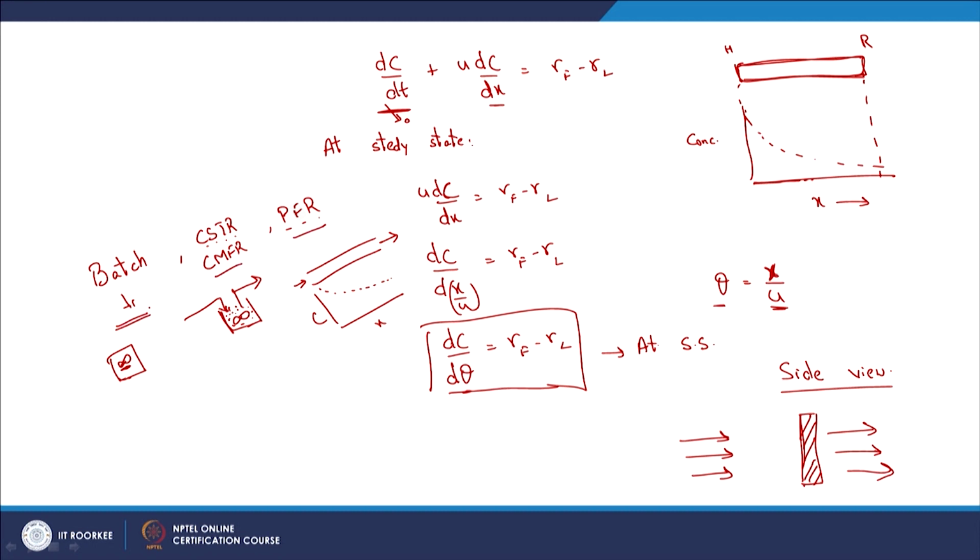Batch reactors have typical applications in any experiments you conduct in the lab. CSTR, or completely mixed flow reactor, applies to most typical unit processes in water or wastewater treatment. For example, in the activated sludge process you have continuous mixing, and you typically assume that the concentration of the relevant compound in the reactor is the same.